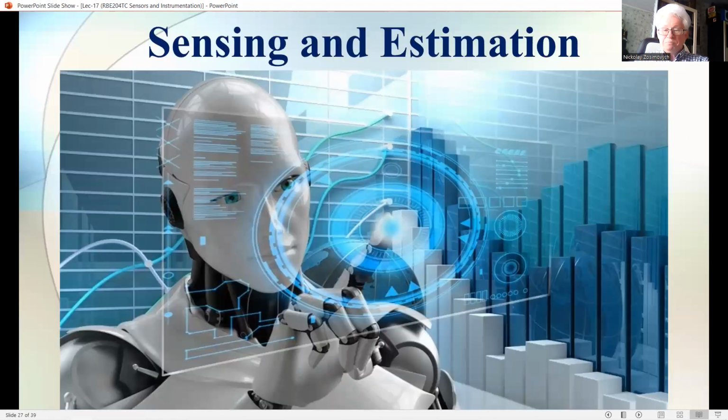And the first subtopic of this lecture is called sensing and estimation. In the use of a sensor system, the measured quantity may be a constant parameter, like the moment of inertia, or the length of a robot arm, or an average property of a batch of items, like the average internal diameter and its variance of a batch of ball bearings.